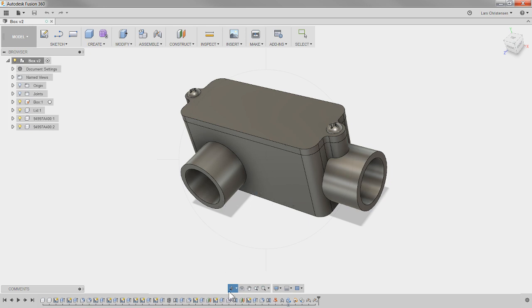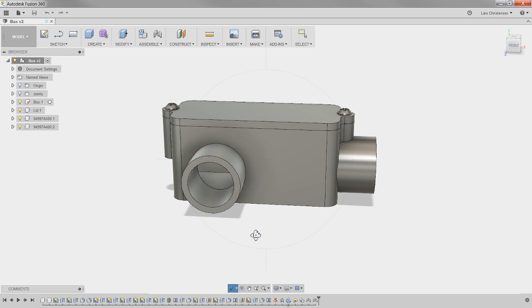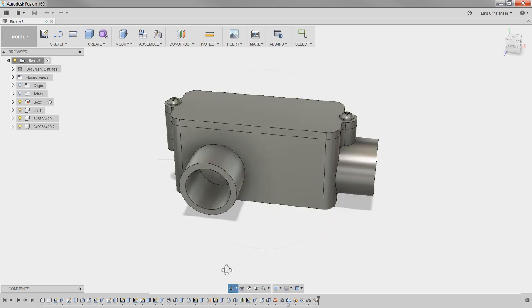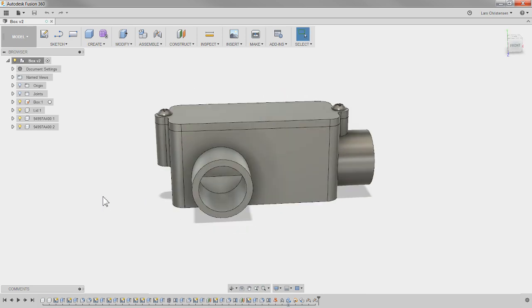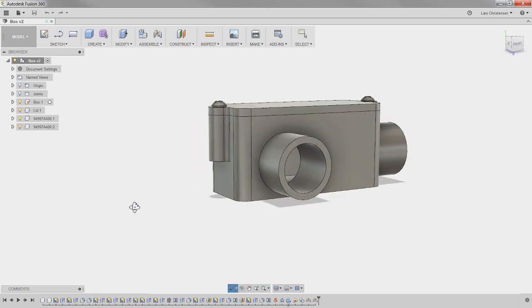Now, I activated the constraint by clicking down here. So right now I can spin around with the left mouse button by first clicking down here. By the way, if you want to get out of this, press escape. And you're out, you're back to normal. So now I could use my shift and middle mouse button to just go in and impulsively spin the model around. But if I want to stick with it, I just click down here, and now it's the left mouse button.